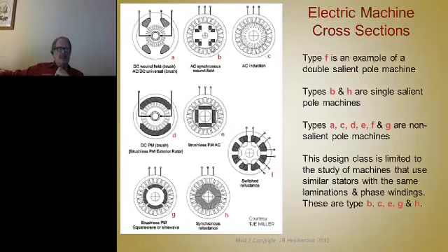In this case, the last thing I wanted to show you was of course the induction machine, which has the same stator as this one, but a different kind of rotor. And we're going to talk about what that rotor consists of. That's a punch lamination with slots in it, and those slots are filled with current-carrying conductors. There's a couple ways you could fill it. You can wind them, or you can cast them in there.